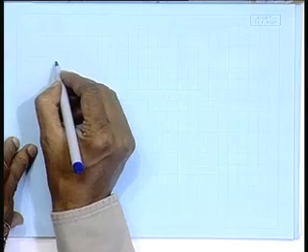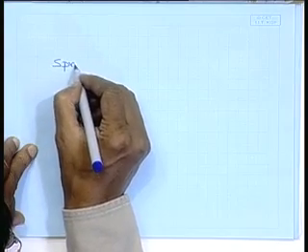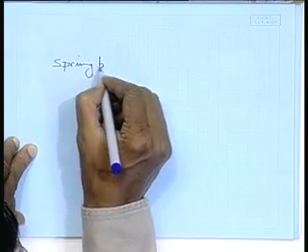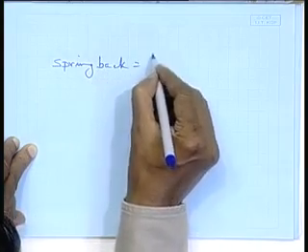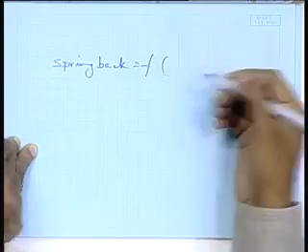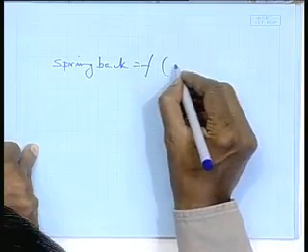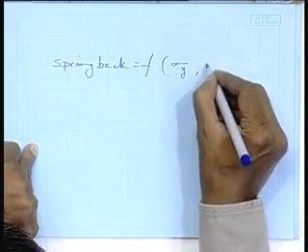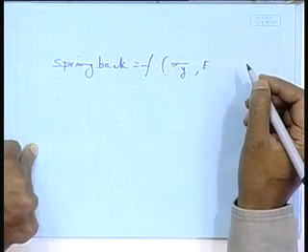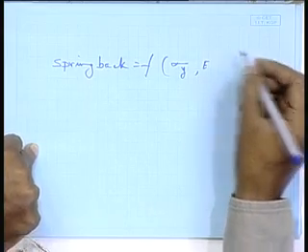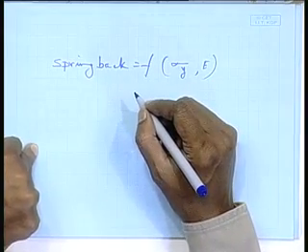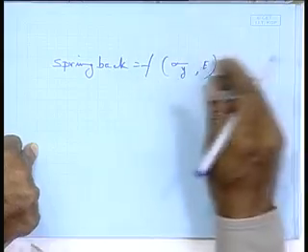Because how much spring back action there would be is a function of what? It is a function of the mechanical properties, essentially a function of sigma y, a function of modulus, right? Primarily these two. And then other things, the dimension of the plate, thickness, etc. But material properties, primarily these two.